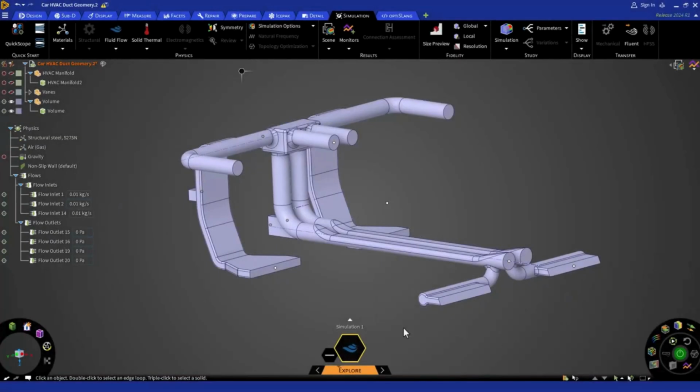In the last video, we learned how to apply fluid flow physics conditions. In this video, we will discuss meshing in Discovery Explore mode. Here we use a voxel-based meshing approach to discretize the whole geometry. This approach eliminates the need for time-consuming mesh generation as the process is fully automated. The discretization techniques and solution algorithms are designed to achieve maximum automation and speed.